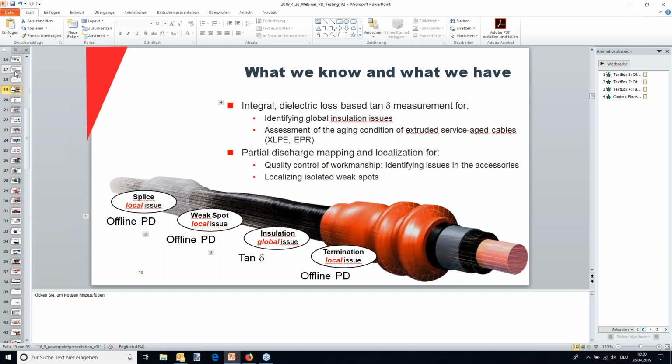And PD in the cable itself, as I said, you would have to have what's called a field intensity related fault, which is the voids, which are very rarely seen these days. The manufacturing quality of Nexans, Südkabel in Germany, Prysmian, General Cable, well, that's Prysmian now, Prysmian purchased them.